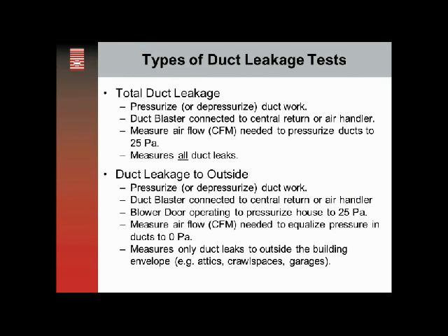So you're going to use your duct blaster fan to get the duct pressure back to zero, and then the CFM that results is the leakage to the outside. So you're measuring only the duct leaks to the outside of the building.